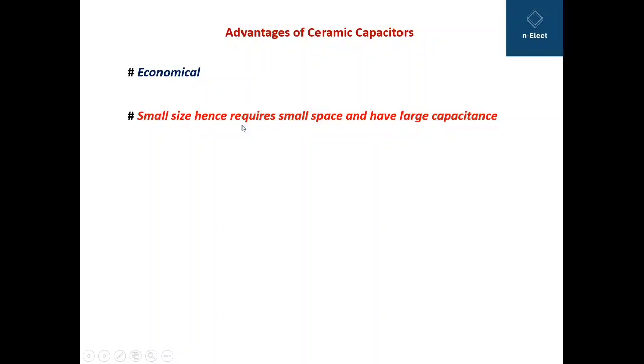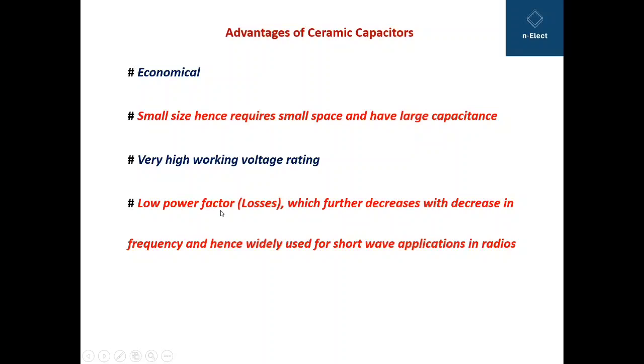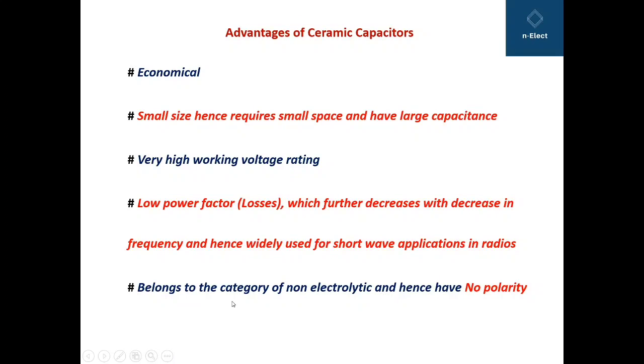Some of the advantages of ceramic capacitors we are going to see here. They are economical, as we have already seen. Small size, hence requires small space and has large capacitance. Very high working voltage rating, as we have just seen. Low power factor, meaning low losses, which further decrease with decrease in frequency, and hence they are widely used for shortwave application in radios. They belong to the category of non-electrolytic and hence have no polarity.